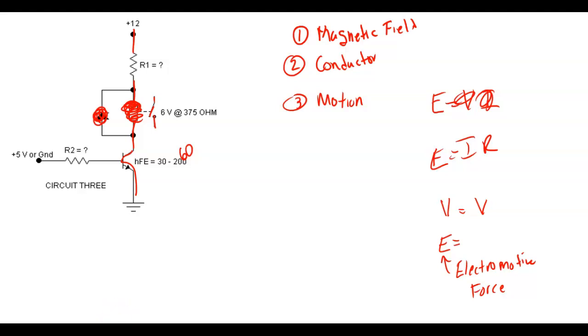So we call this a flyback diode. They call it a counter EMF diode, that guy right there. Like I said, we can take you over to the Amatrol line, or over to the Festo line, and every relay you're going to see they have a what? They have a diode that's reverse biased across the port. So y'all understand what's going on. That sucker puts out over 100 volts when we discharge.